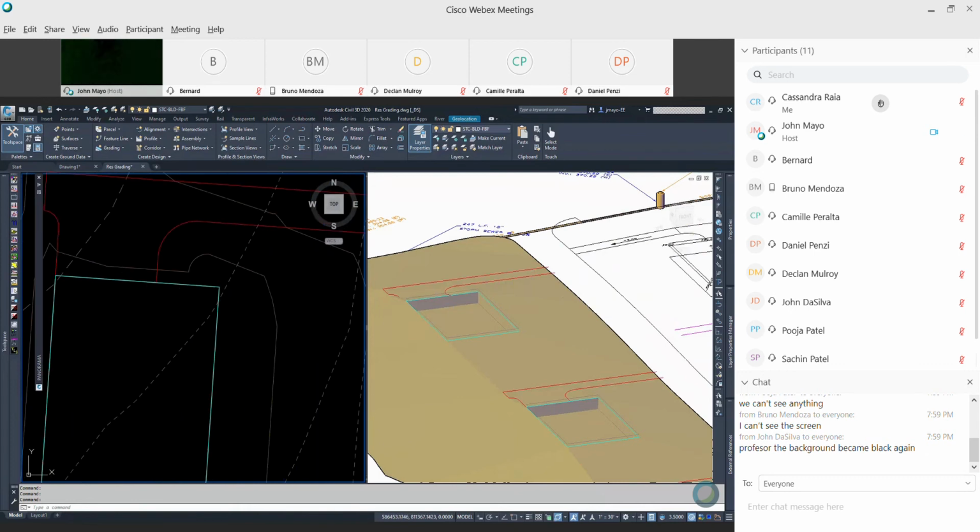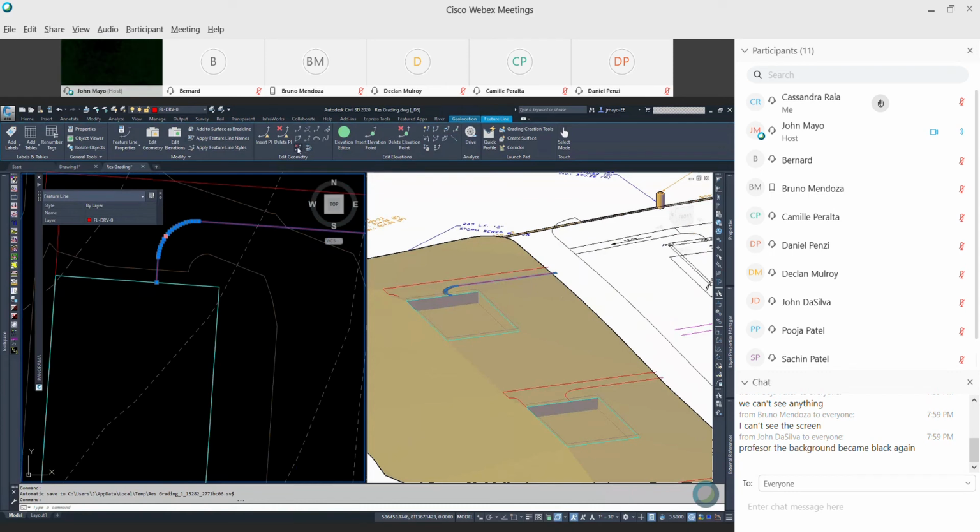I'm going to take this driveway and just assume the wall is connected to that driveway. And I'm going to offset that feature line with the stepped offset. I told you guys you can use a 1 foot width to help with your grading. It's not realistic unless you're putting up a formed concrete wall. But for now, just use a 1 foot width for your wall in plan view. And I make a top of wall break line there.